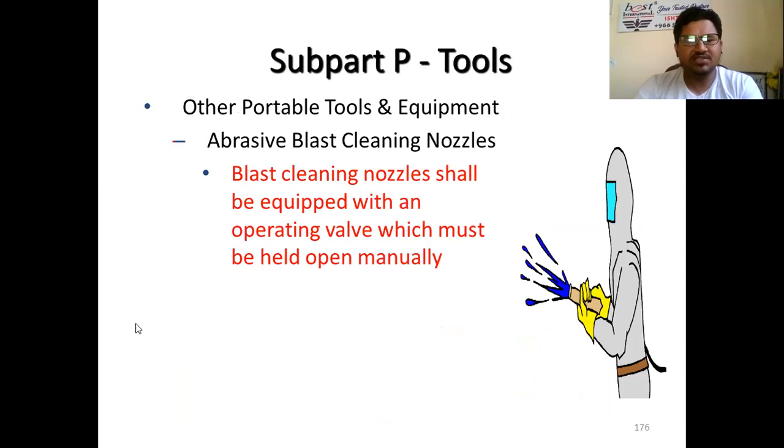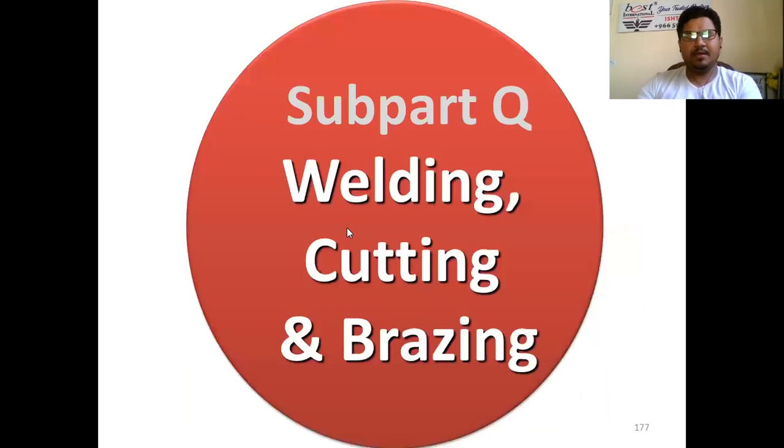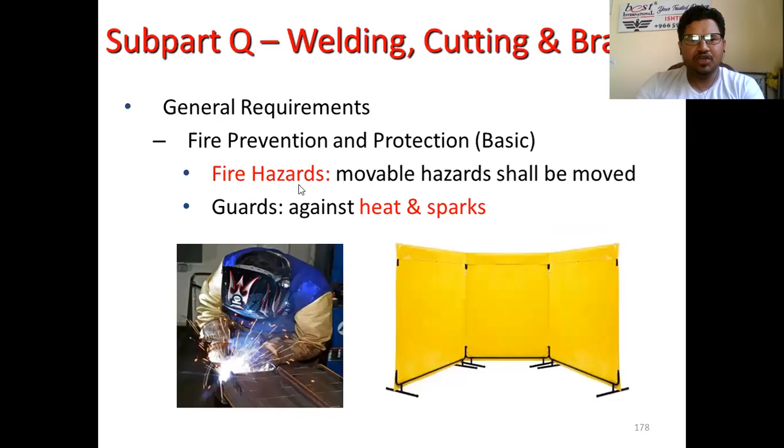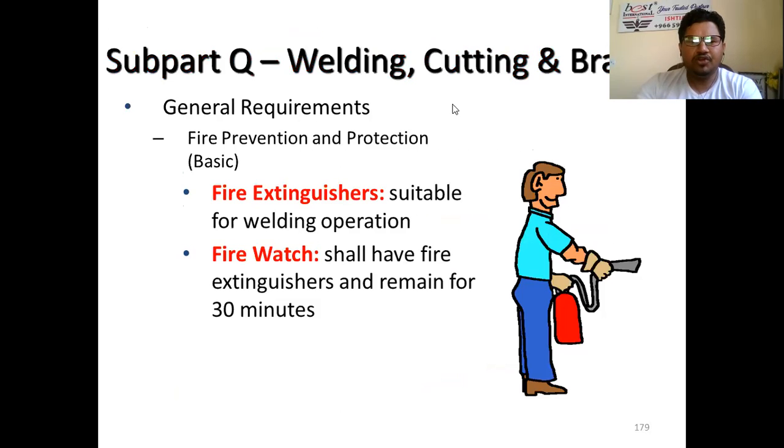If you're doing sand blasting or abrasive blasting, make sure the blasting cleaning nozzles are equipped with an operating valve, which must be held open manually as well. Now, welding cutting is subpart Q, welding, cutting and brazing. We're going to use welding, cutting and brazing, fire prevention and protection, like fire hazards. Movable hazards shall be moved, guards against heat and spark. Make sure you have a proper fire extinguisher and fire watch, and the fire watch must stay a minimum of 30 minutes, even after hot work.